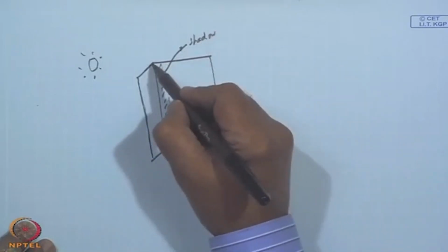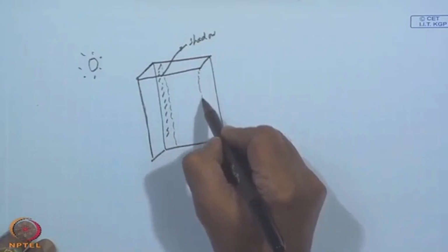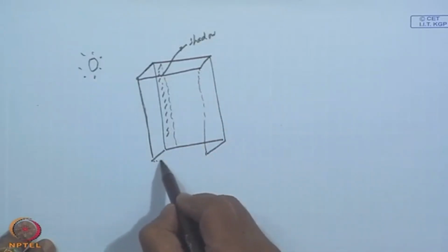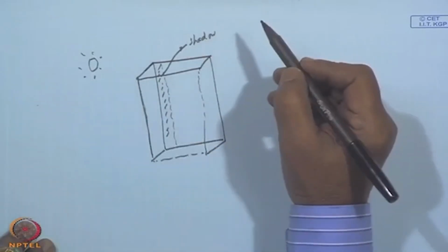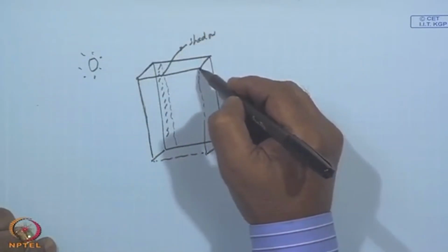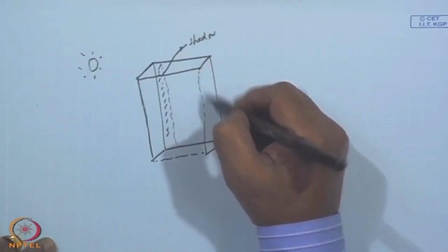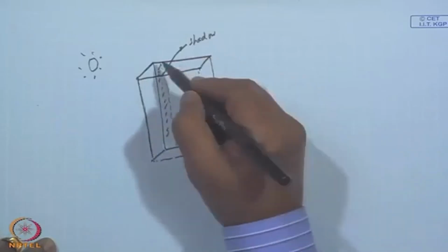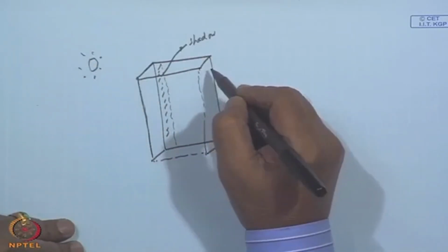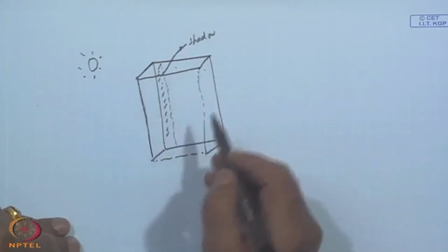So, if you have an overhang and two wing walls, and bottom is not necessary, but usually that makes it a box type window, there will be pretty good coverage. I have not yet exactly made the calculations, but I suspect that if you have got wing walls associated with the overhang, you may treat the overhang as if it is infinitely long, because it is either shaded by this or this. So, that is a different issue.